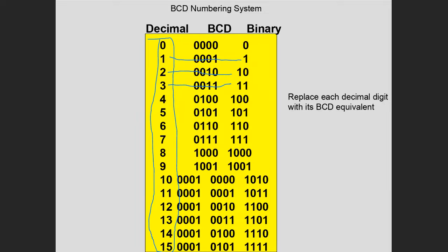But notice what happens when I go over to the count where I have 2 digits, like right here. 10 in decimal is a 1 and a 0, right? It's a 1 and a 0. Well, in binary, a 10 base 10 is a 1, 0, 1, 0 base 2. If I do my 8421 code, this is an 8, and that's a 2. 8 and 2 is 10. So a 10 in base 10 is a 1, 0, 1, 0 in binary.